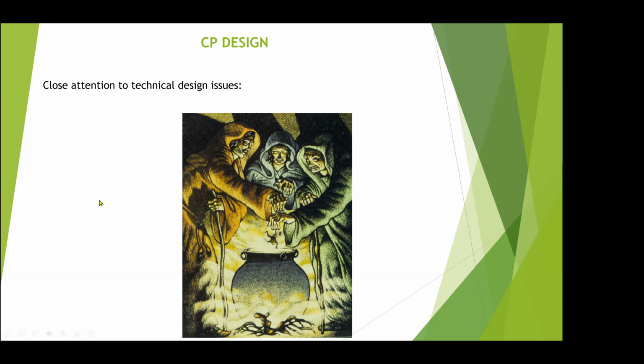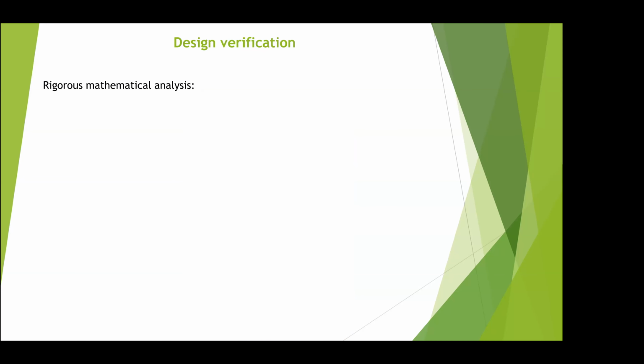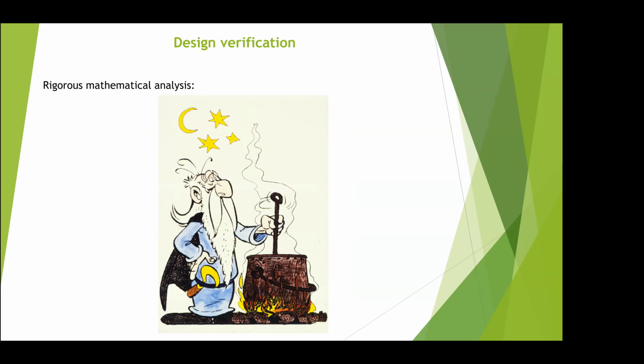So basically, there's an awful lot of guesswork in CP design because we have to try and guess what the performance of the coating is going to be like over the time. We have to guess whether or not the operation of the pipeline is going to change, whether there's going to be a new railway coming along, whether there's going to be overhead power lines, buried power lines, and all kinds of things. So the cathodic protection design is usually quite conservative. And of course, somebody somewhere sometime has to do the maths, and this has to be checked by a qualified CP specialist, in this case, a Frenchman.